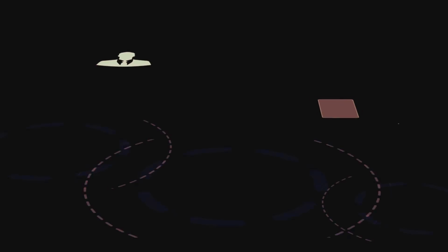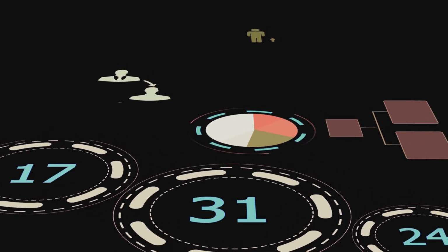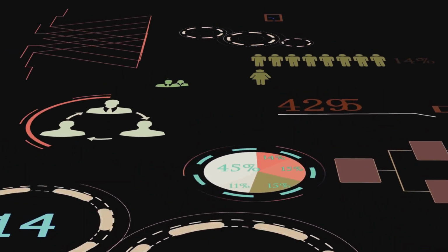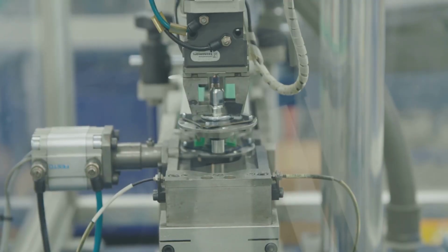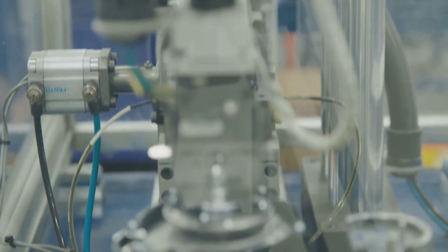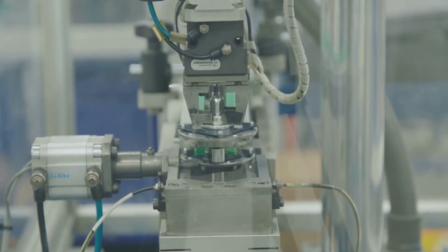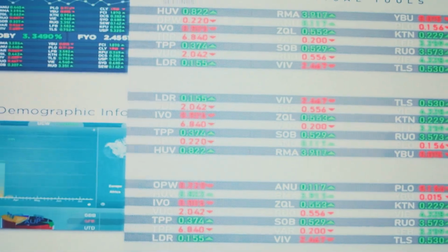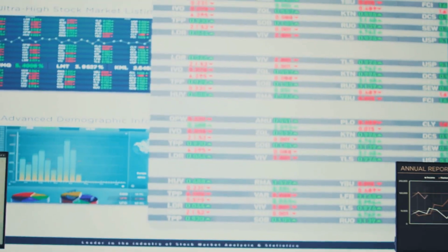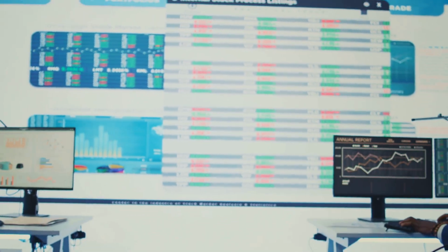By plotting your data points on the chart within statistically calculated control limits, you gain a visual representation of process behavior. This allows you to see the true rhythm of your process, understanding its natural flow and identifying any disruptions. Control charts effectively separate the signal, the meaningful changes, from the noise, the random variation, giving you deep insight into the stability of your process and its overall performance over time.